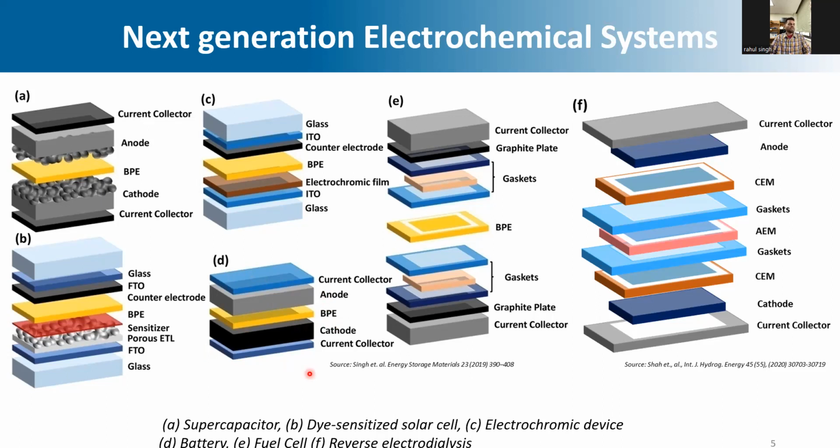So our target is to make a strong and reliable, stable system. If we are not using a strong membrane, or if we are using something fragile, then the electrodes, the anode and cathode, can get shorted out, and it can generate a lot of heat, which can result in fire. This is one example with lithium-ion batteries. This is happening with fuel cells also.